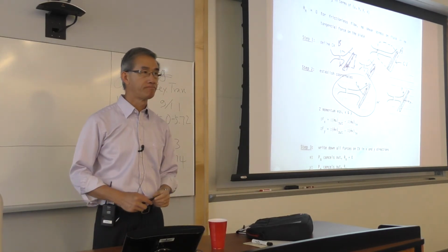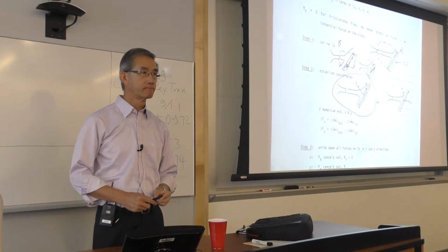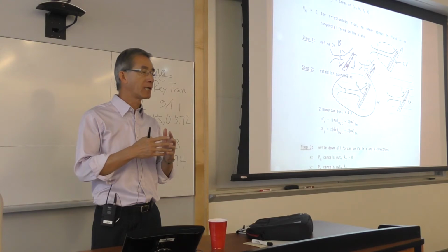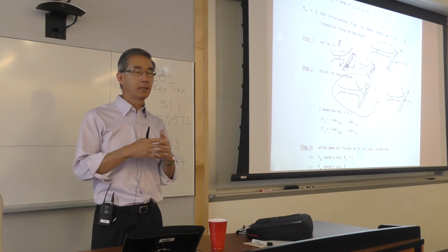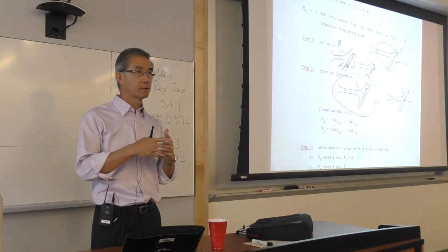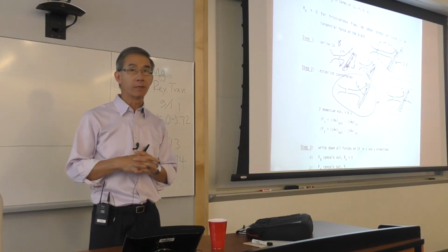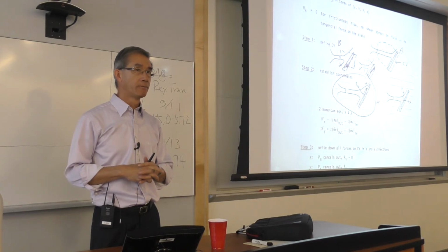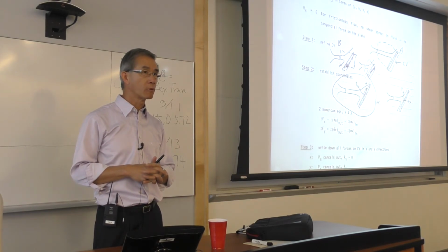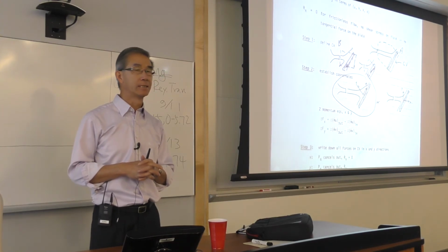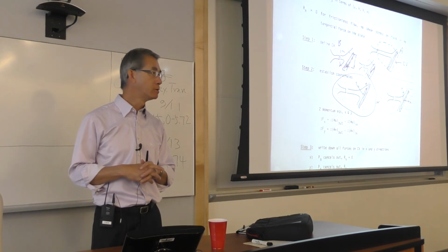We're adjusting our axes to go in the same directions that the resultant forces are going in. Yeah, you choose your axis so that they're parallel to the two unknowns Rx, Ry. And the key and the hint is to recognize Rx along the plane is 0 because it's frictionless. How much more work do you think will be added if you choose the right-hand side coordinate? A lot, more than an hour.